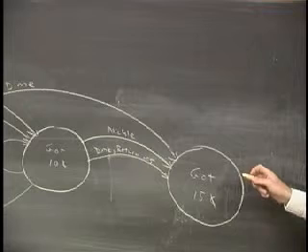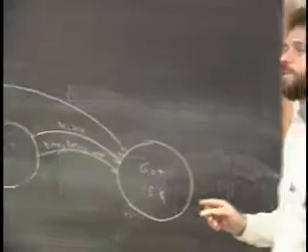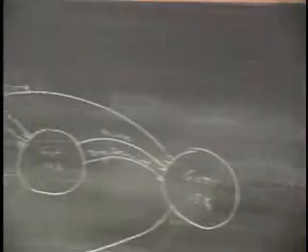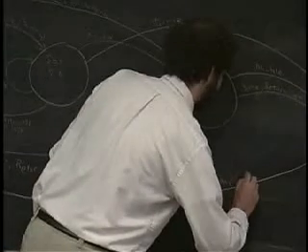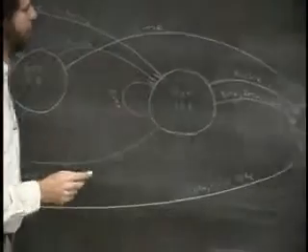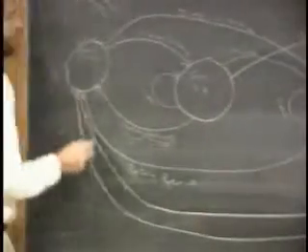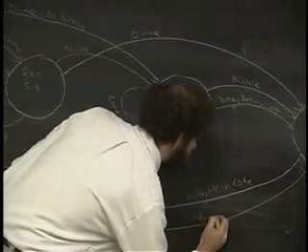Well, if the person presses the Coke button, it gives them a Coke. Go back to the initial state. So another big arc over here saying if they press the Coke button, then we want to drop Coke and go back to that state. The return button over here, same sort of deal. Here's return, and we want to give them 15 cents back. Right? Return 15 cents.